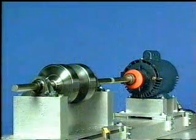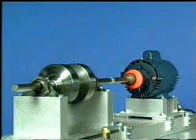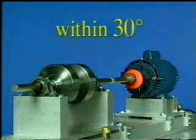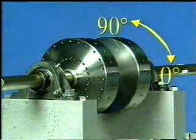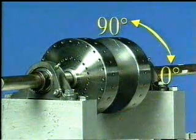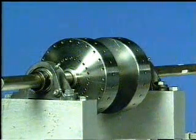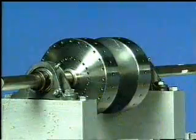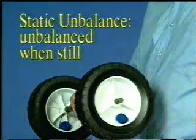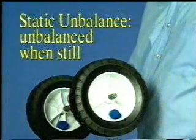As a rule of thumb, when diagnosing machinery conditions, most actual machinery phase measurements will not be exactly in phase or exactly out of phase, but should be within 30 degrees. Phase measurements from the horizontal to the vertical position at the same bearing location should shift 90 degrees, since the sensor is moved 90 degrees. These conditions are typical of a static unbalance condition. Static unbalance is a condition when the rotor is unbalanced, so that when it is at rest in a frictionless bearing, the heavy spot will swing to the bottom.